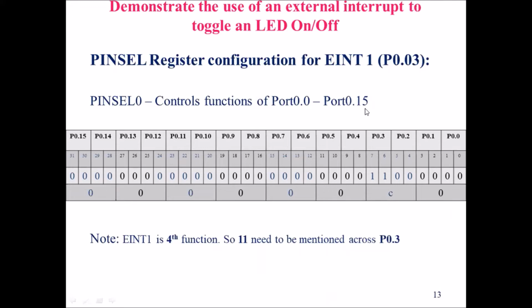How many ports are associated with the PINSEL0 register? It will be 16 ports, ranging from port 0.0 to port 0.15. For these 16 ports, we make use of the 32 bits that are available in the microcontroller. You can see here the bits range from 0 to 31, so a total of 32 bits.